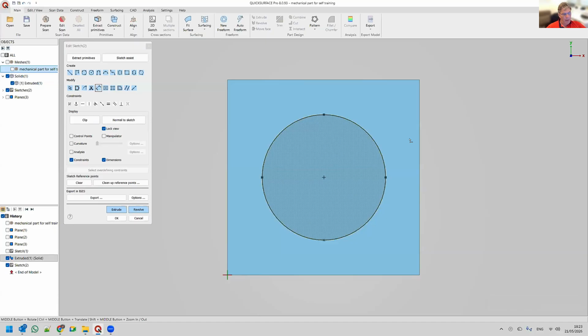we have the same as in any CAD package. I can just put the dimensions. In some packages, it's called smart dimensions or just dimensions. What you see on the screen is that the software determined that this radius should be 19.9994, which for the machinist is a nightmare. You don't want this to be this dimension. So you have the full control to just put in the correct value and then work in the correct way.